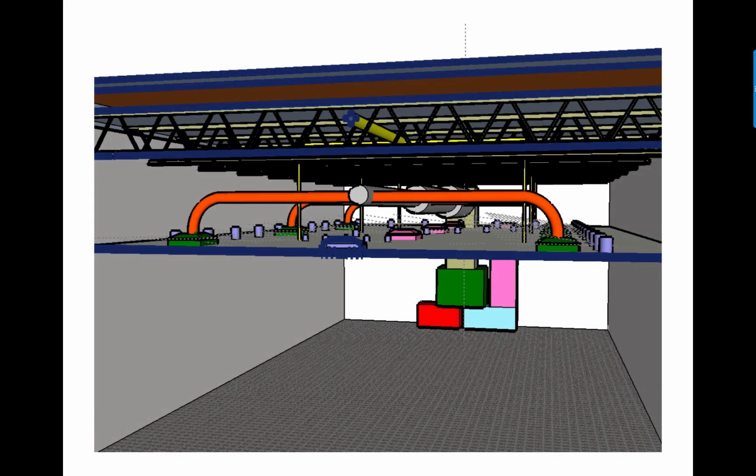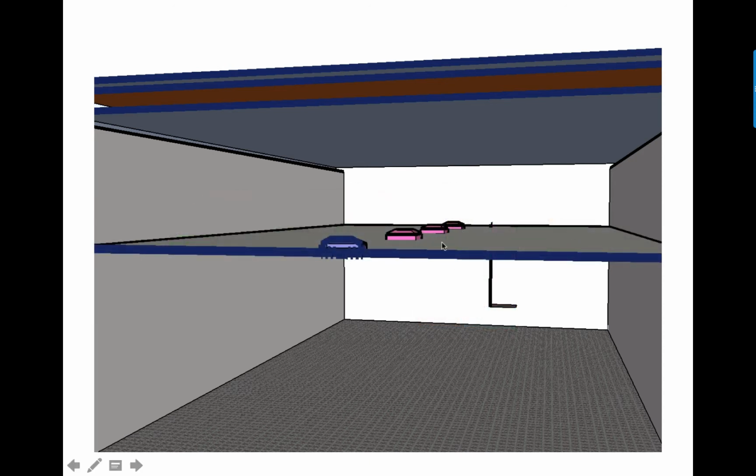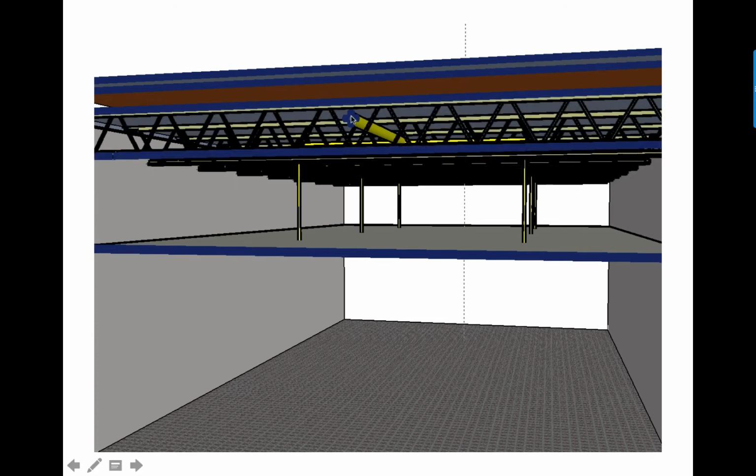And I did this little diagram to indicate to you all the junk that goes up in the ceiling. You start with your HVAC system, and this is kind of what we have in our classroom. You have a main trunk line, which often can be quite large, and then you have these sub lines that come out. And then you have return registers in the ceiling, and the whole ceiling is basically acting as a giant duct, which is kind of not so great because they get pretty dusty after a while. Then you have your sprinkler heads in there, and everything wants to be right in the middle of the room, which is why if you have an open web steel joist, at least some things can squeeze in between those joists.